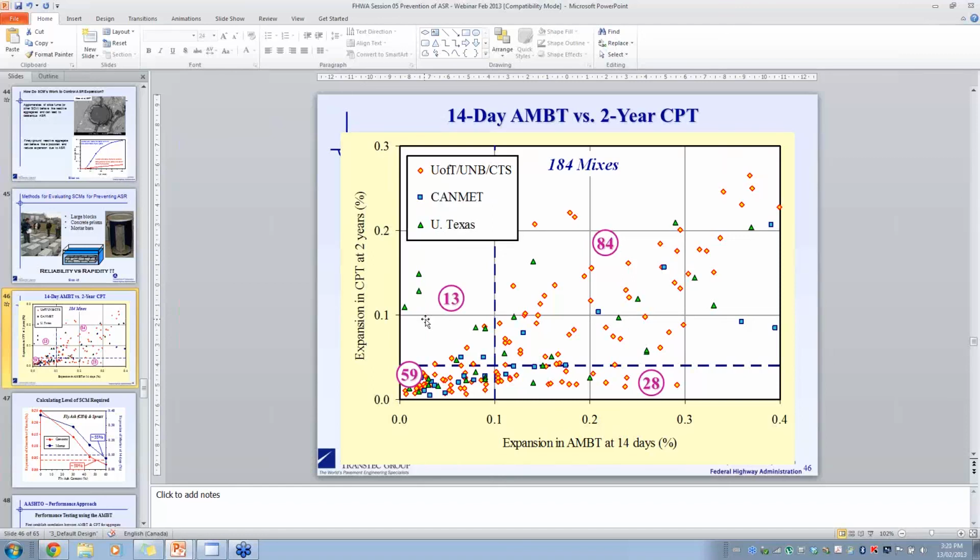I would say to a great extent that changes in mechanical properties are not really the significant issue with that structure. It's dealing with the growth and the expansion and the cracking. That's really the problem. I don't think there's really been any indication that the structural performance of that concrete has been drastically affected.